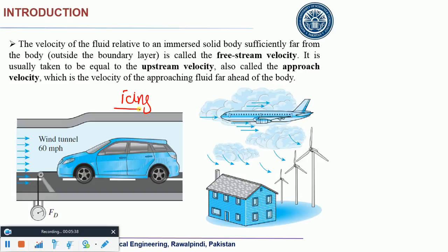Generally, if you are dealing with jet engines at that height, you can consider how big a problem it can be. It would deteriorate all the aerodynamic performance, all the thrust, all the drag, or whatever it is. Power requirements can change as well. Now it means you have to do something to take care of the heat transfer so that there can be a phenomenon known as de-icing. You need to get rid of that icing. So this is related to heat transfer.